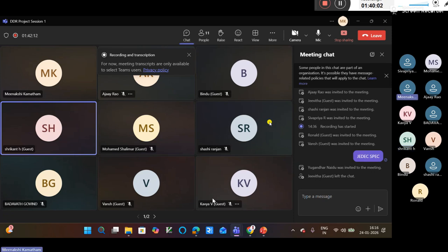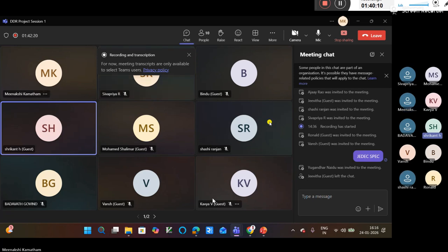Yeah, Shrikant. And having some memory knowledge is helpful, like how read and write happens, the basic cell structure, then DRAM being based on capacitor charge, how it stores the bits. That is basic, but then rows and columns, row decoders, column decoders. Those all are the basics, but those who have this memory idea only will know.